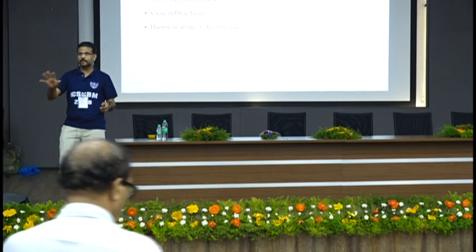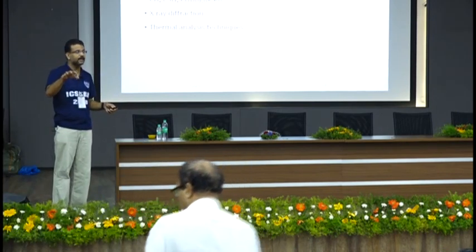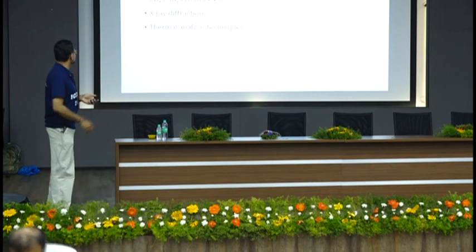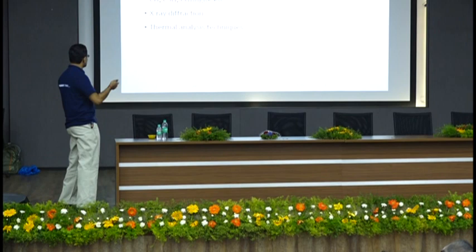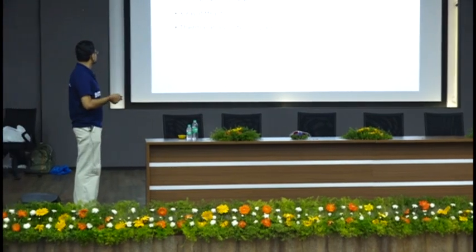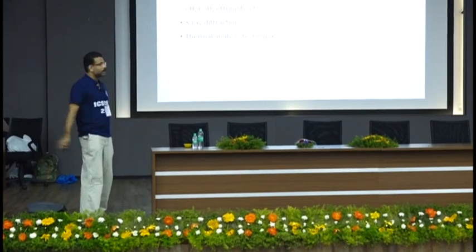Okay, so let's start with hydration product analysis. So the pore structure story is done. We'll do the hydration product analysis. So basically, how much of CH, how much of CSH, how much of ettringite. We'll do X-ray diffraction and thermal analysis. That's all we'll do for the time being because these are the easy techniques.